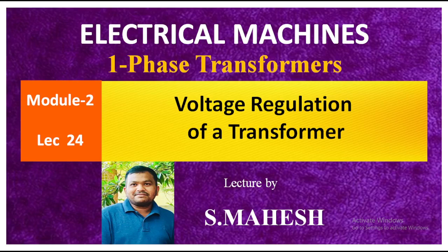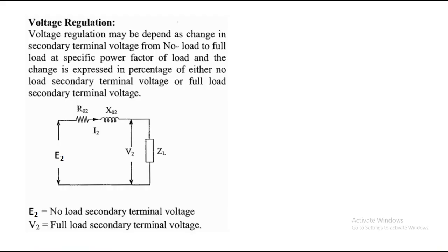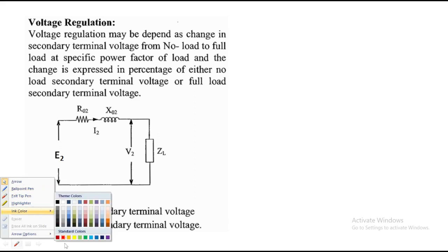Hello everyone, let's discuss another performance indication of a transformer, that is voltage regulation. So what is the definition for voltage regulation? The voltage regulation depends on the change in secondary terminal voltage from no load to full load at a specific power factor.